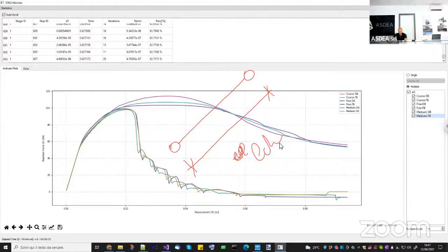But now there is a problem. This kind of definition for characteristic length is fine for a displacement-based element because a displacement-based element assumes a pattern of deformation. Now, in this case, it is a curvature, which is linear. Okay, so all the points here, all the Gauss points, will localize. In a force-based element, instead, it is different. In a force-based element, what we assume is not the curvature, but the bending moment.